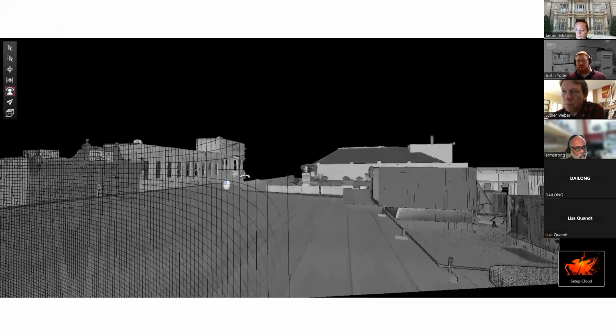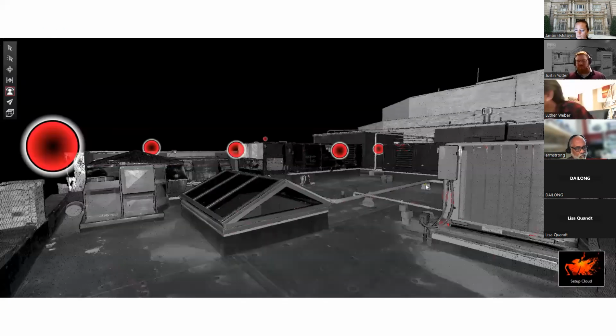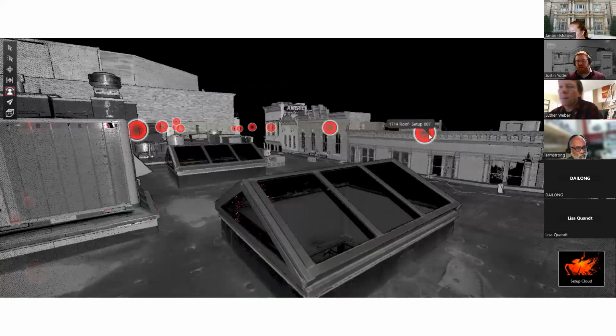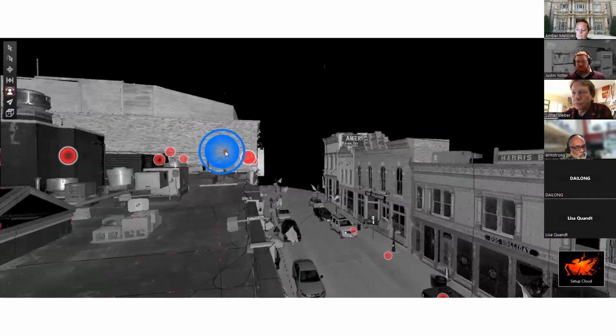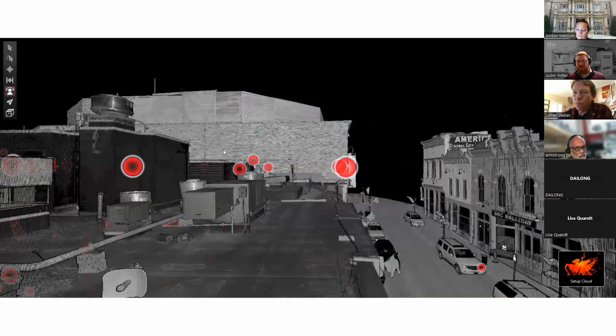Each black and white point or pixel is a representation of an actual laser measurement, accurate down to less than 2 millimeters. This means that this entire 3D picture you're looking at is dimensionally accurate. And we use this data to help an architect identify floor sagging, wall sagging, and other structural issues before a major remodel of this 100-plus-year-old casino in Colorado.